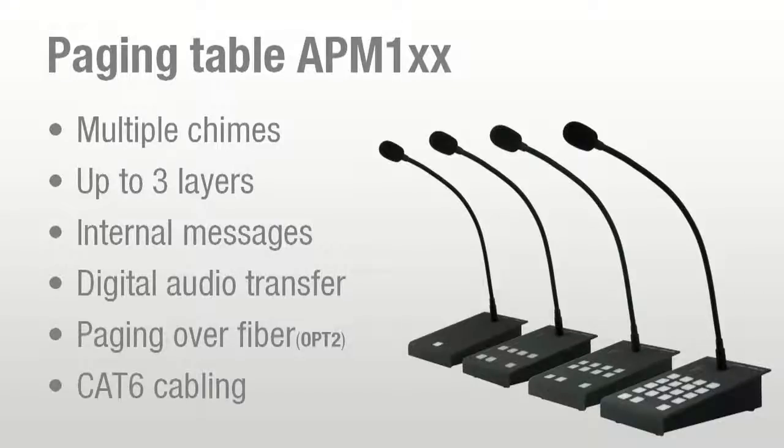The paging table. It can contain multiple chimes. You can program up to 3 layers in the APM 116. It can hold internal messages for evacuation. It also digitizes audio locally in the table and sends it digital to the M2. Paging can be done over fiber to other R2s and M2s, and also all cabling is done by Cat6 cabling.